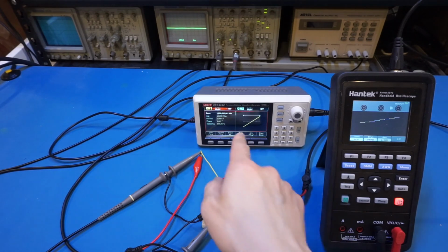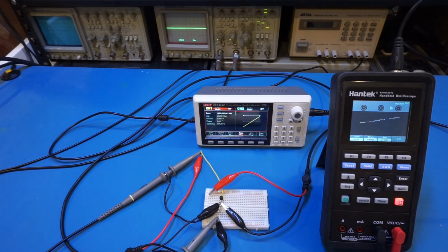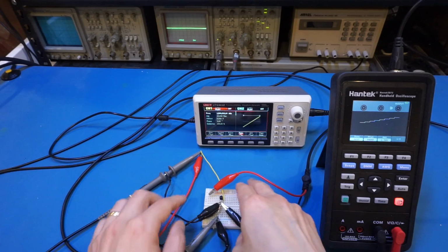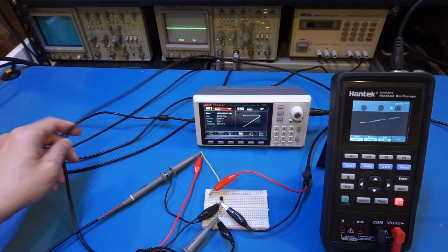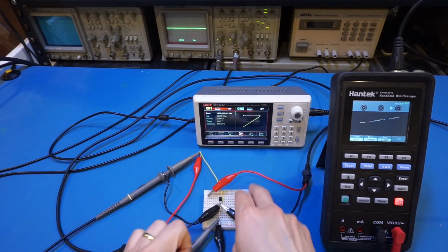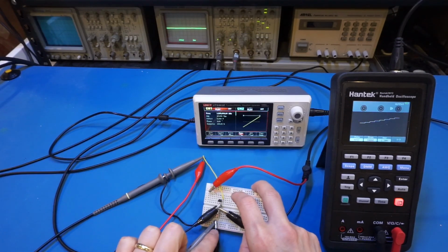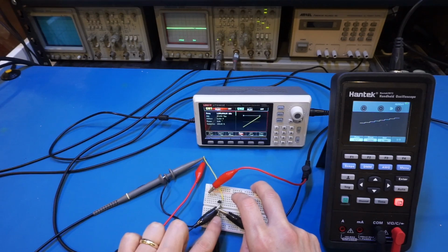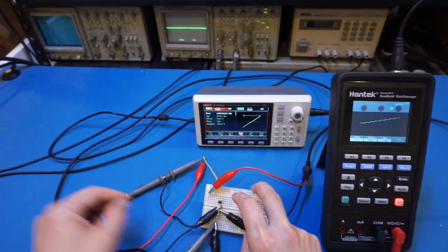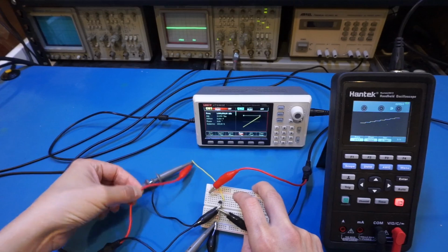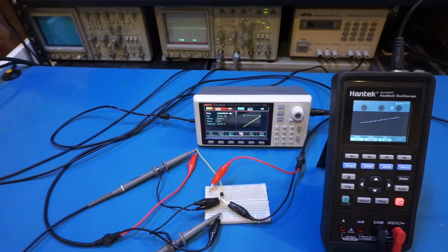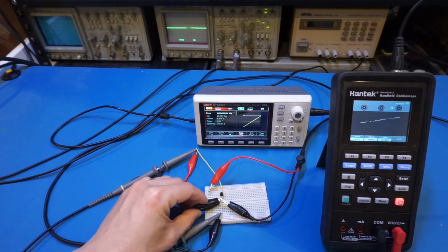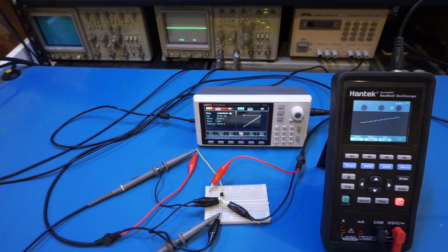The sawtooth signal generated by the UTG 962 goes to sweep the collector and emitter. As you can see here, the output is this lead, and you can see indeed the ground ties to the bottom of that emitter resistor that we mentioned earlier, and the positive goes to the collector directly. The scope leads from both channels are grounded at the emitter here, as you can see.